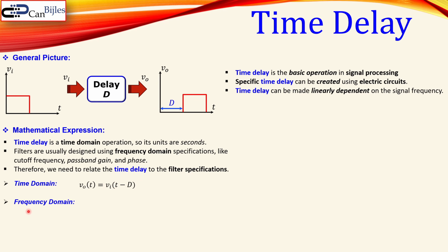But you can also do it in the frequency domain. First we of course transform that in the frequencies using the cosine expression where you see the amplitude, and the omega where you see the radians per second. And this is for the input as an expression. The output is then the delayed version where you replace this t for your input by t minus d, which is actually shown here.